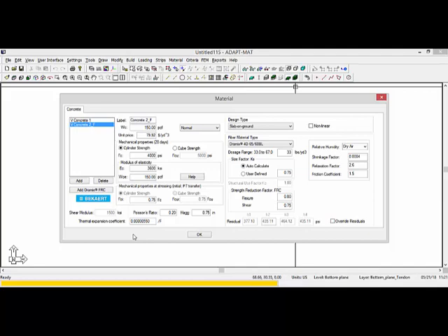Now there are additional options or variables that have to be selected and defined. For example, we have a size factor that's applicable to some of the strength calculations that are made using this fiber type. We're going to auto calculate the size factor. We also have strength reduction factors, which are used for fiber specifically. These are in combination with any reinforcement or post-tensioning that might be used for the system. And we'll leave those to the defaults shown here. Additionally, for a slab on ground with fiber, we can take advantage of the nonlinear response of the slab.